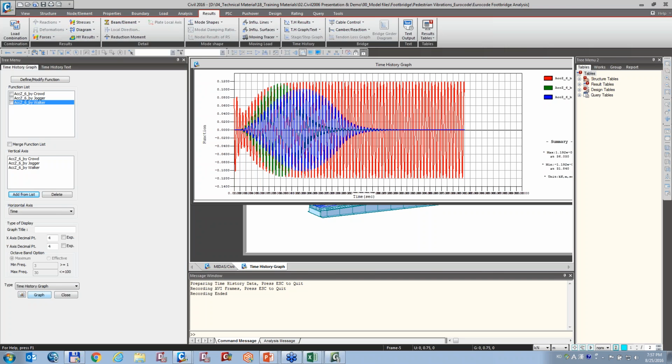Another question is about adaptive pushover analysis. As of now, adaptive pushover analysis is not implemented in Midas 7. And the other question, how can we assign the diaphragm for the slab for the curved structure, curved slab, for example, or the inclined plate.